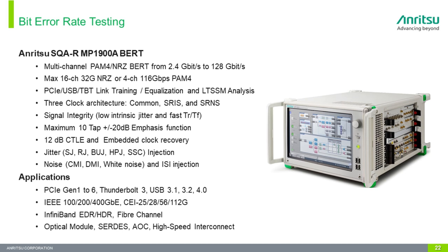The signal integrity of the PPG is a great advantage, with very low intrinsic jitter and very fast Tr/Tf. On the error detector side, there is a 12 dB CTLE. The PPG side has a maximum of 10-tap emphasis, and each tap can be adjusted plus or minus 20 dB independently.